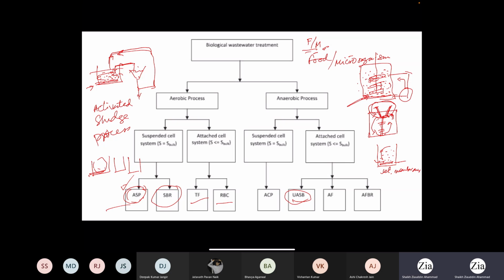In the first reactor, suppose you do a little bit of carbon removal, and then some removal of nitrogen or conversion of nitrogen to nitrate. In the second reactor, you maintain slightly different conditions to target removal of other nutrients. In this way, you can have multiple reactors operate in a sequence.